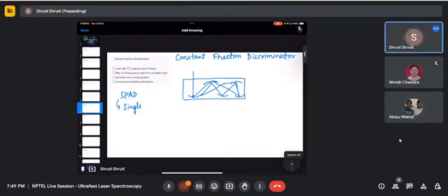So here we were discussing the constant fraction discriminators. If you go into the mechanism, it will be very difficult for me to explain. But what it does, simply, is this: if you have two photons whose signals got emitted at the same time but have different amplitude, in the case the capacitor which got charged was different for them, this instrument, the constant fraction discriminator, equalizes them.